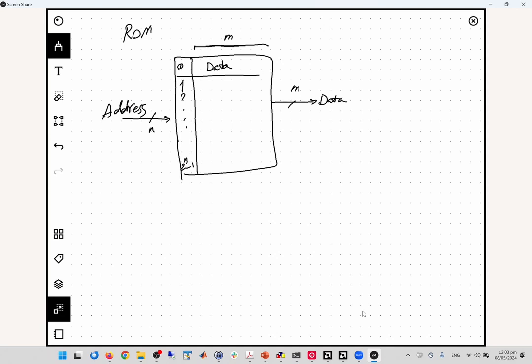And then suppose that this is just a lookup table, and if you are able to configure this chip as a lookup table, then this n-bit address and m-bit data are available as the primary input and primary output on the chip, then you can realize any function that you want. Of course, as long as the number of inputs that you want to give the circuit is not larger than the number of the address bits.